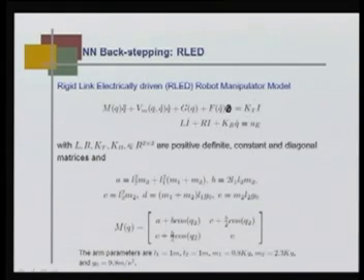You know that this is actually torque, and torque is the torque constant times current, and then we can write the motor equation as L i dot plus R i plus k_b q dot is u_e,